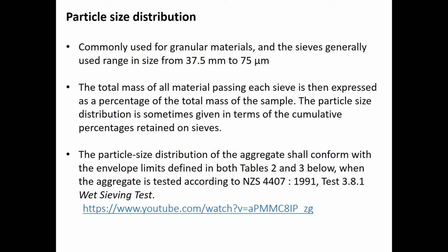Actually, the contractor will specify the particle size distribution required for the project, and then ask the people at the quarry to mix it ready, and then they bring it to the site. But they need to check on the site as well, to see whether the particle size distribution follows the spec or not.